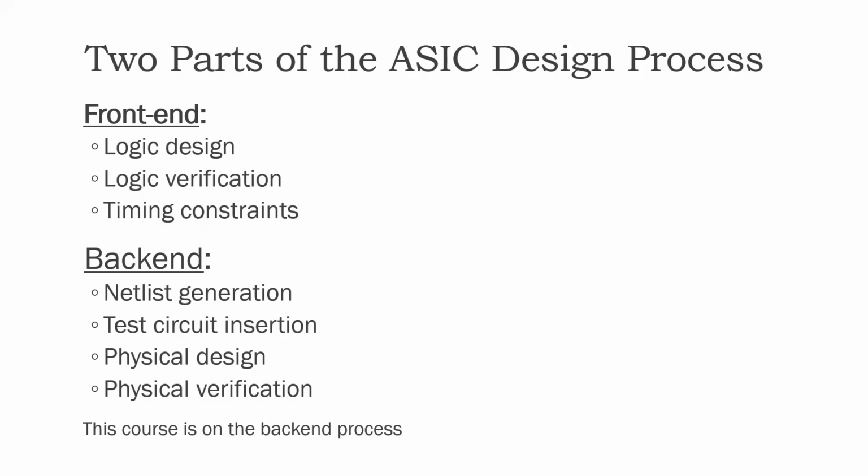The timing constraints, it may not be clear to you what they mean, but that will become clear as this course progresses. For now, just note that the design of an ASIC involves the design of logic as well as formulation of the timing requirements. What types of clocks are there? What are the clock frequencies? What are the input and output delay requirements? Those constitute timing constraints. So these are the three primary aspects of front-end ASIC design.